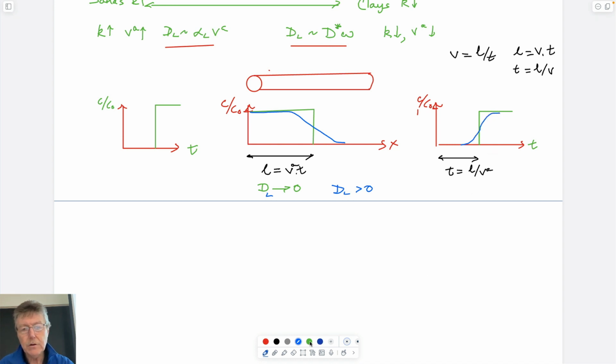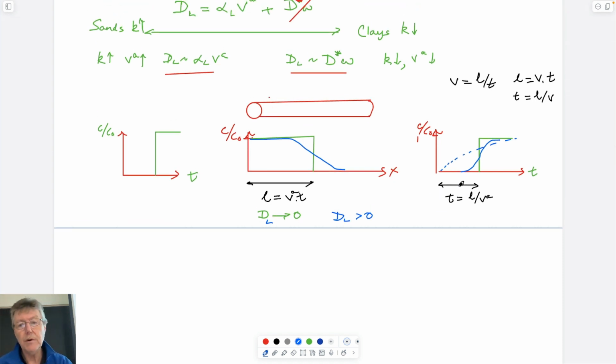And we even saw in some cases that these curves would actually look like this. These are the same. This is for plug flow: you get a sudden breakthrough, and all of a sudden it turns on and turns off. We talked about the reasons for this being that it finds some fast pathways, which allows it to arrive early, which is what this is saying.